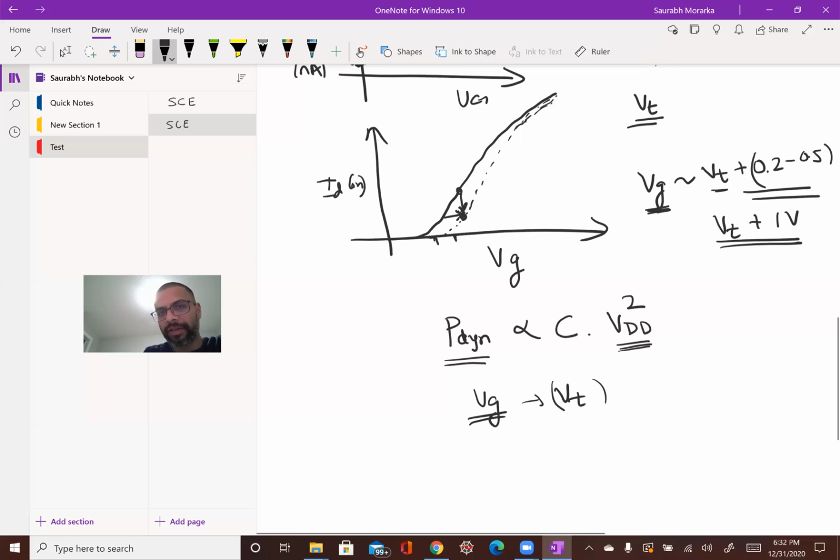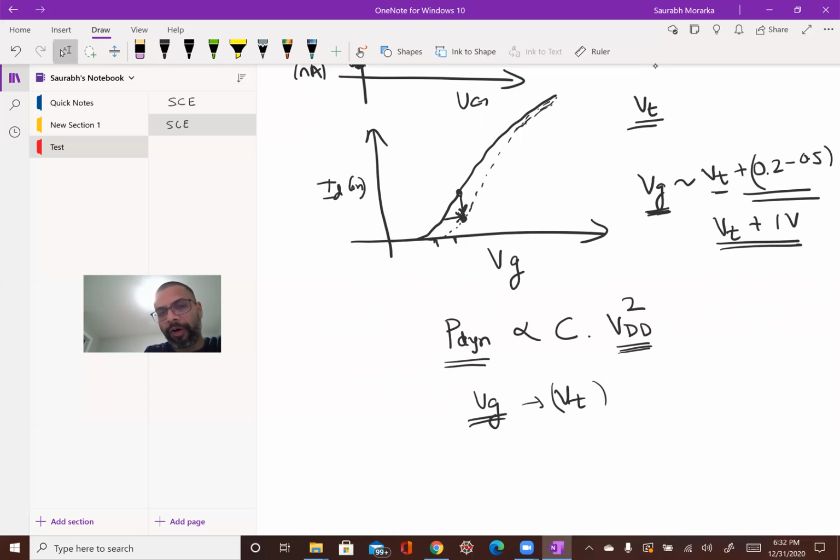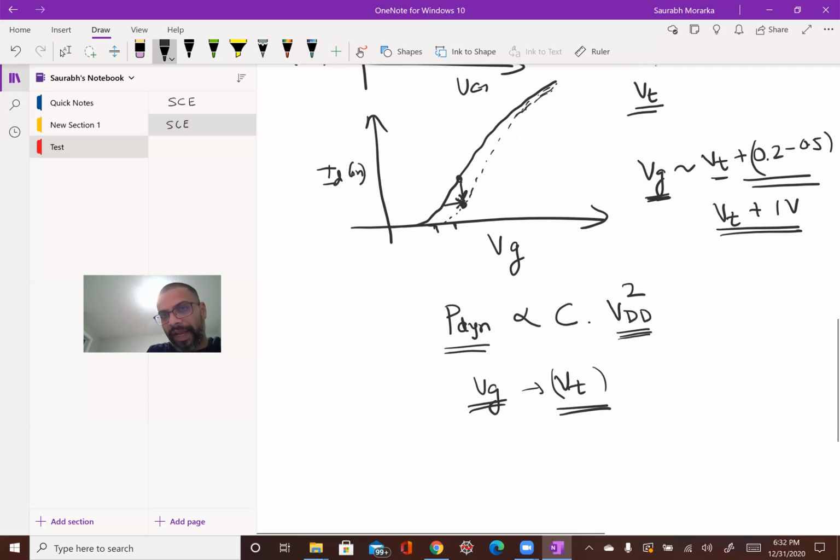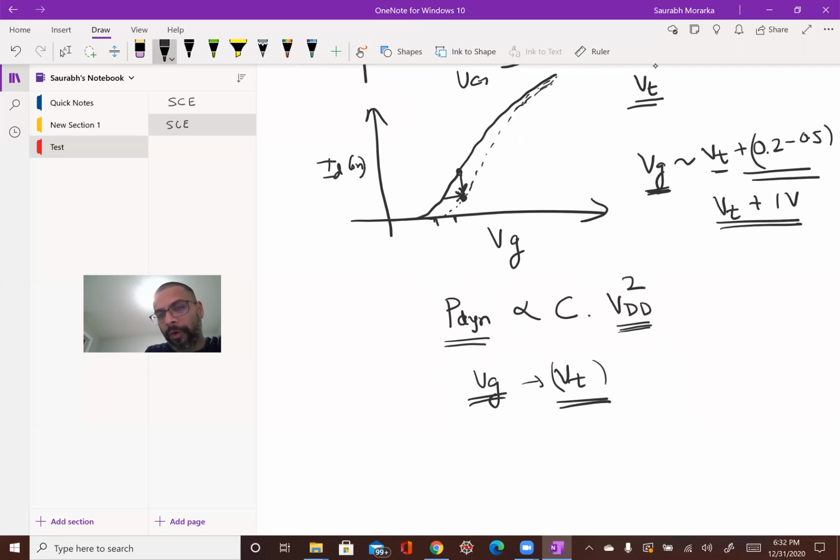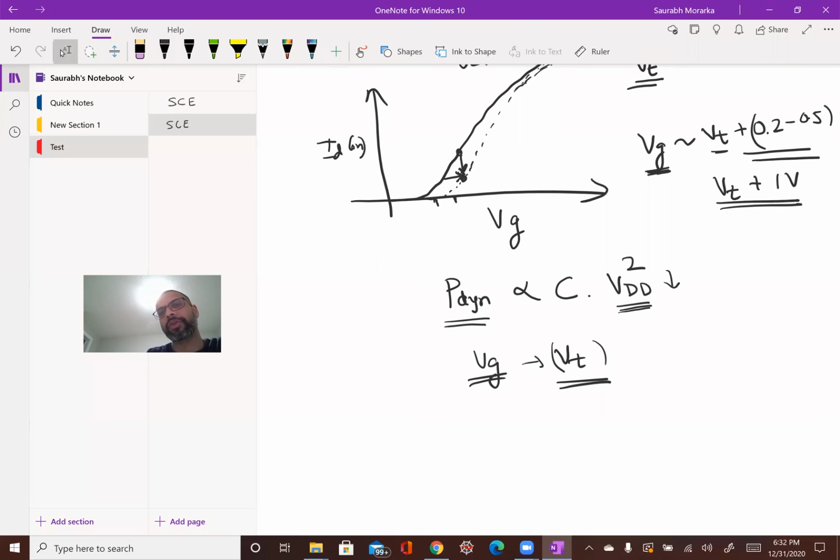If they degrade, the performance, which is ID on, suffers the most. And hence we care about low VG points near the VT a lot more, because the VDD has been constantly going down. And hence the short channel effects can really degrade a device, because we can somehow reach the off-state current by changing the VT or the work function.